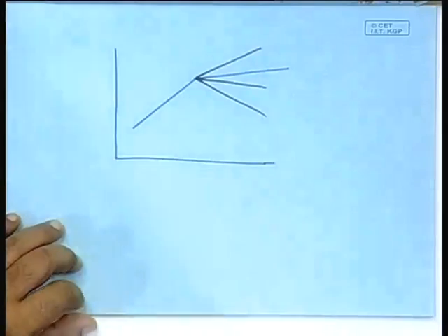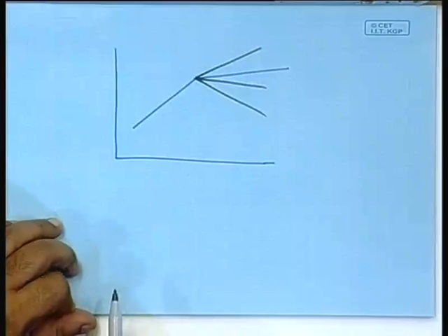Now, in any real system there is some kind of noise, so that due to the noise there will be some oscillation, and there are two orbits that are arbitrarily close to each other. What does it mean? It will keep on jumping between the two orbits, and as you change the parameter their distance increases, and finally the system gets locked to one of them. Which one? There is no guarantee, and it is not difficult to see that there is a fundamental source of uncertainty as to which one it will lock to. So, this is a typical situation that can happen in non-smooth systems that people have come across.